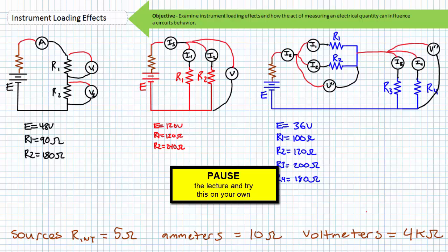For circuit 2, the 3 ammeters, the internal resistance of the source, and the voltmeter in parallel quite obviously change the nature of our once pure parallel second circuit into an ever so slightly more complicated series parallel circuit. This should still be well within your reach. I'm asking what the ammeters and voltmeter read at their given locations. Be aware that the single voltmeter in this circuit isn't really measuring V1 and V2, but rather the voltage across 2 parallel paths consisting of an ammeter in series with a resistor. We'll discuss these subtleties in the analysis.